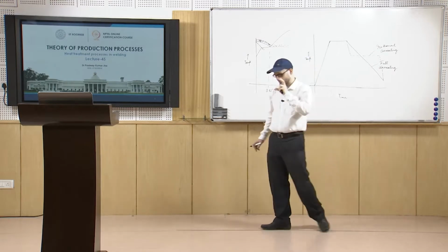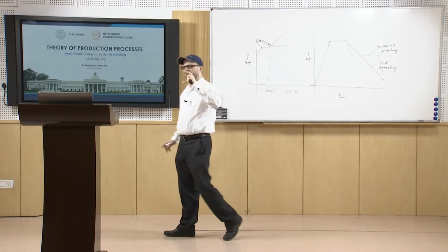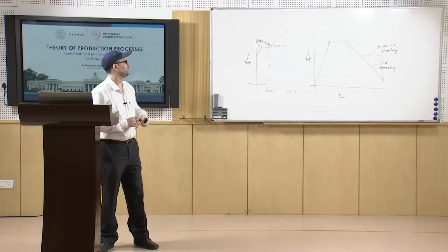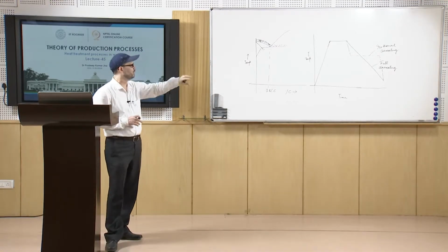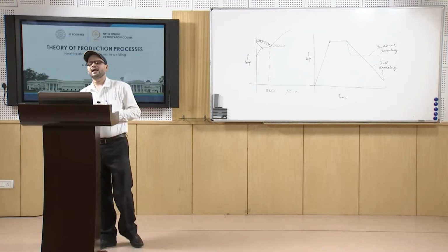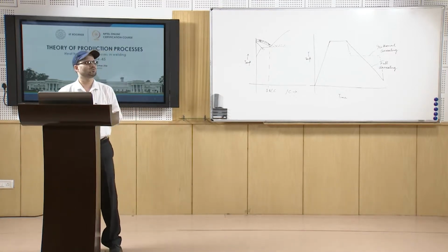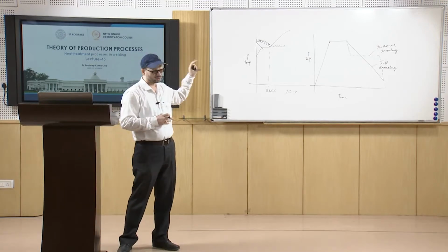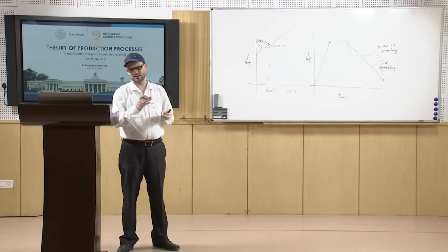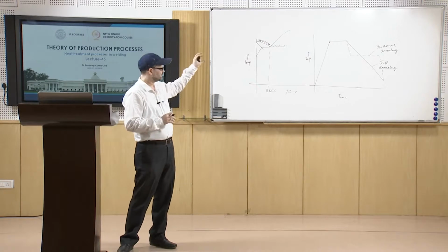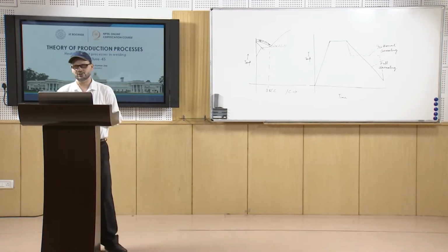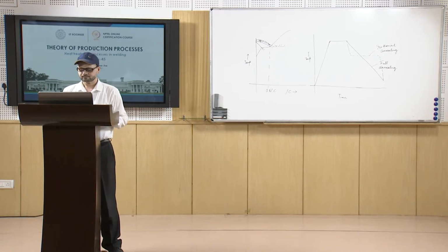So, there is fast cooling from there, whereas you have slow cooling in the case of full annealing, and here the fast cooling leads to a finer type of structure. In full annealing, since you are cooling at a very slow rate, you will have coarse pearlite, whereas in this case you will have the fine pearlite structure.